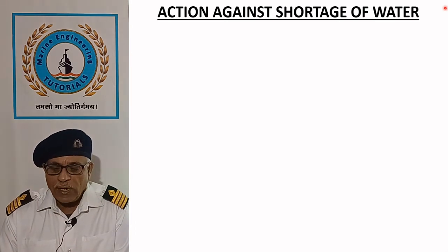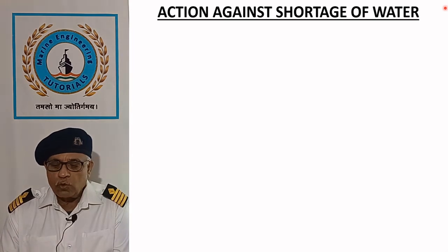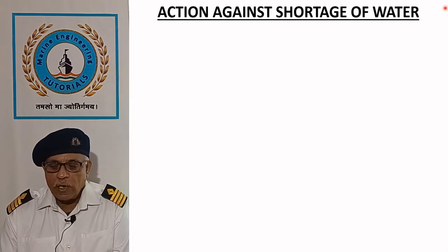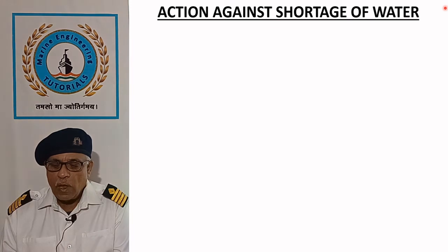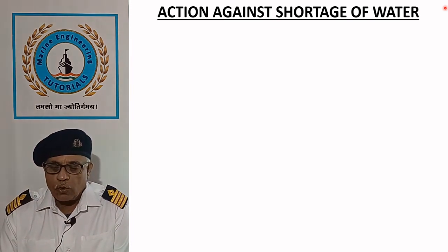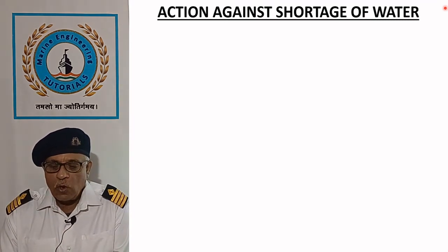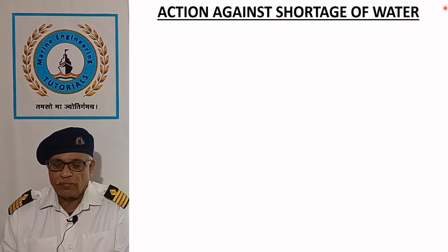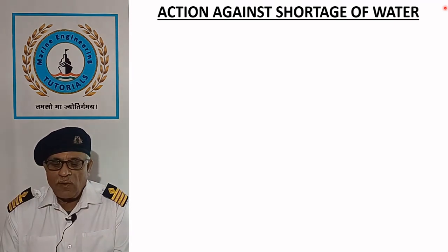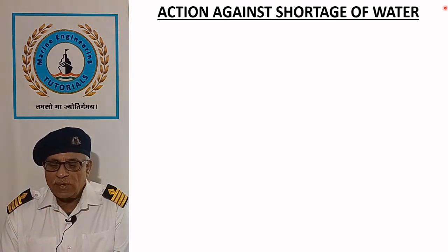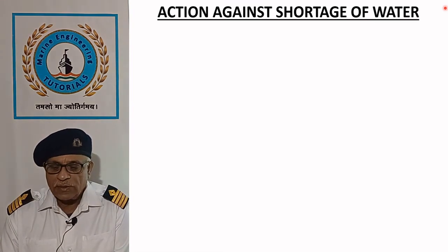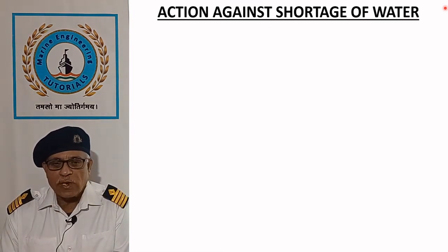Boilers are adequately protected against low water level by way of 2 direct reading type gauge glasses and 1 remote water level indicator for manual control. An automatic feed water control system and safety system equipped with low water level alarm and trip. In spite of all these, if water level is not visible in the gauge glass, following actions are immediately required.